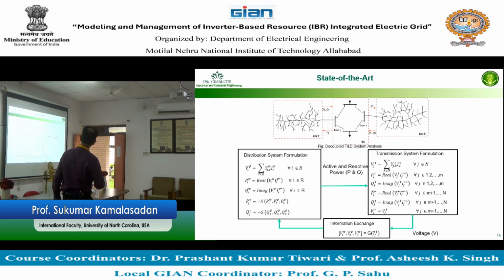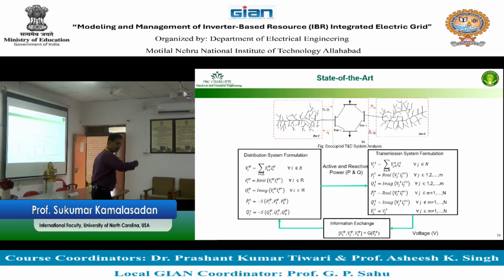Now, when you run this, will you be running multiple iterations? Yes, you will run multiple iterations until you come to a point where the errors are minimum. So when do you know when to stop for the whole thing? You look at the voltage at the bus which is connected and see, as you keep running this loop, whether that voltage between the previous and the next iteration is the same or very close.